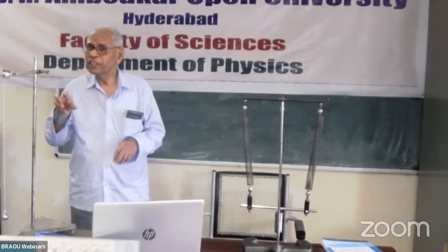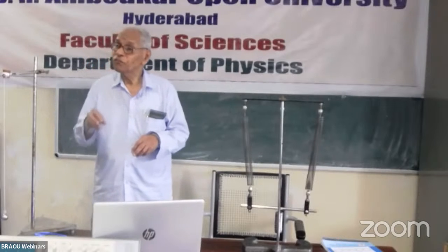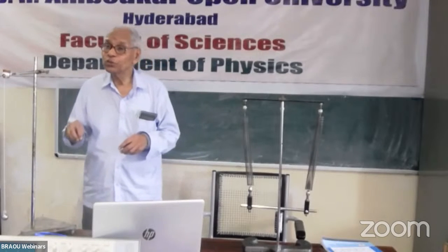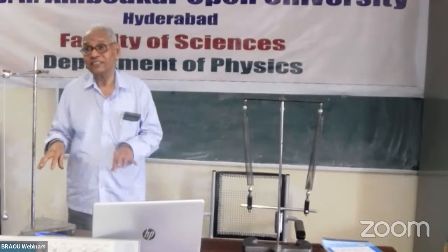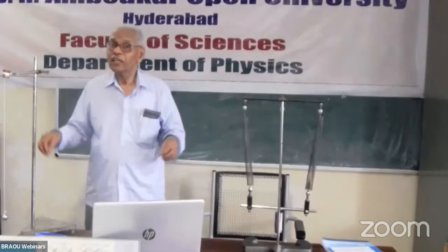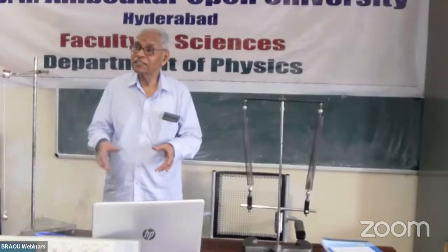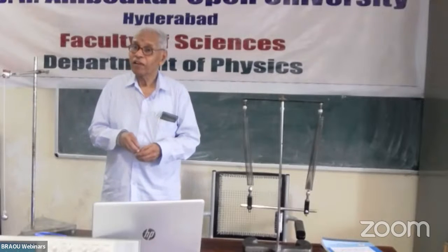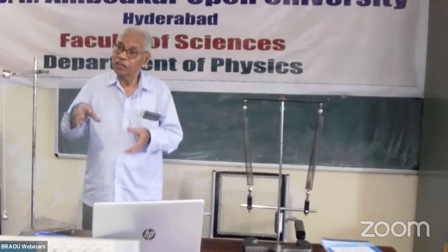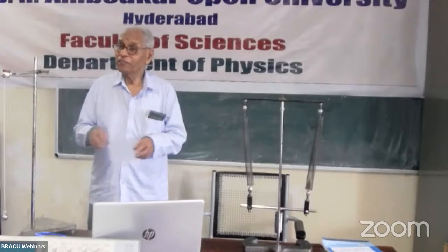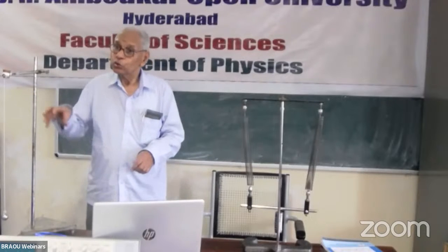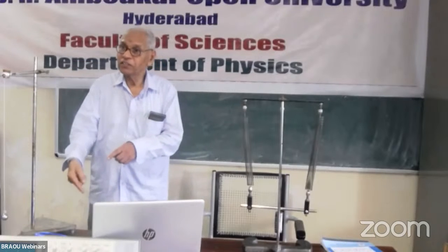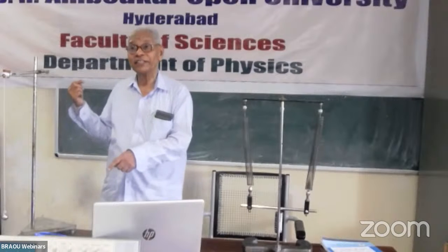Ultrasonics using probes, transducers, can also be used for non-destructive testing. In metallurgy production, there will be inspection of how the metals or alloys are coming out for very important applications. They put the transducer and the wave is transmitted into the material and reflected back.